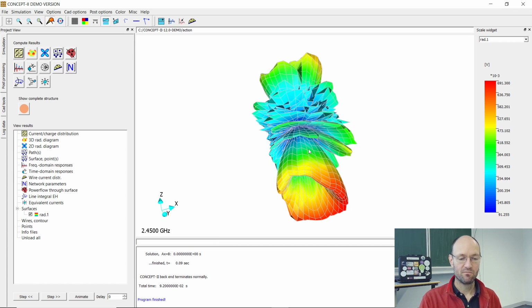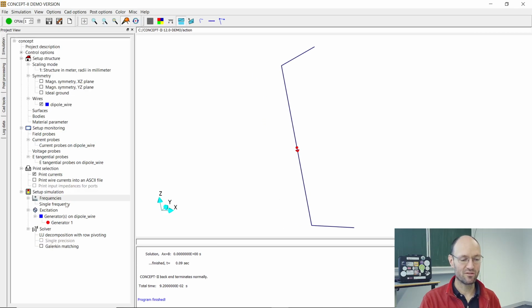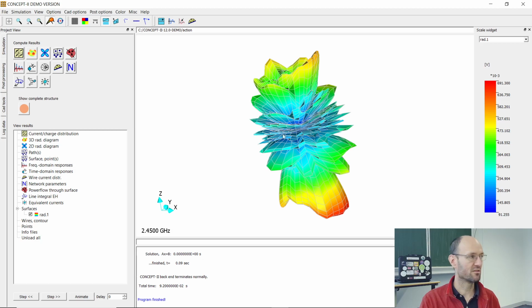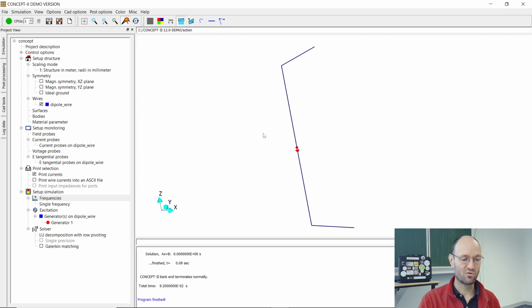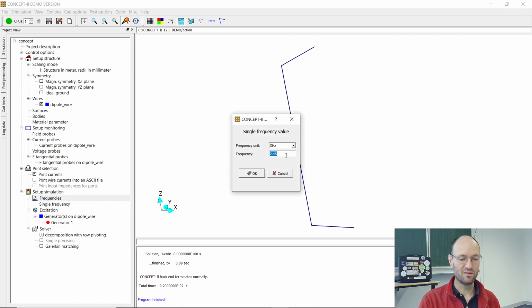Okay, the good thing is, by my small frequency selection mistake, I've more or less already spoiled the answer. So now we could add more complexity. We could add another wire and so on, and make this more complex, and then this radiation pattern would get also more complex. The good thing that saved us in EMC the last decades is, however complex your structure is, if you once again go down in frequency, so if we go back to the 1 megahertz or even 10 megahertz that we had before. Maybe it even works with 100 megahertz still.